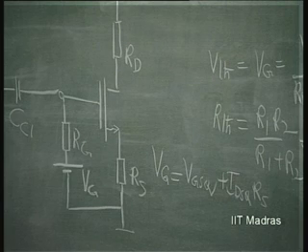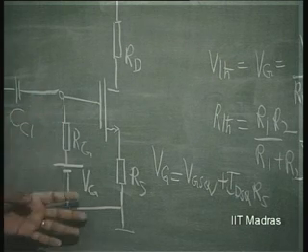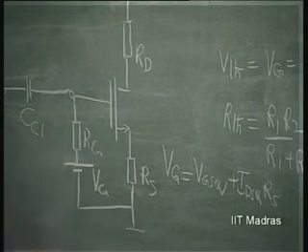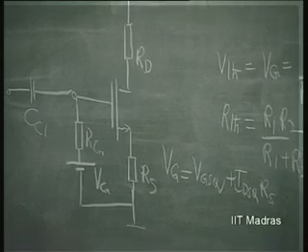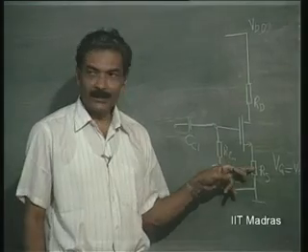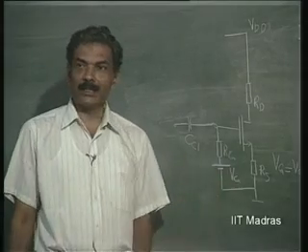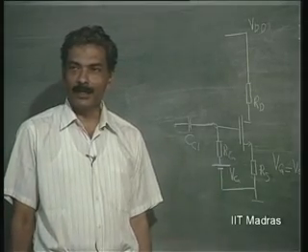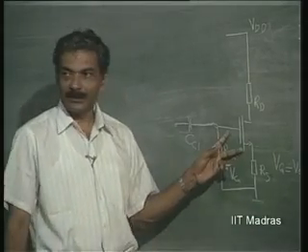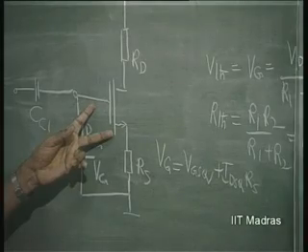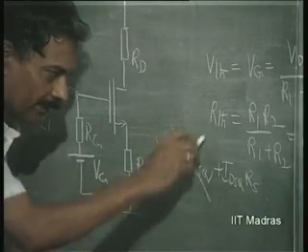Is this clear? This voltage earlier was becoming totally equal to VGSQ, that was giving problem. So, what I did was put a resistance in series with the FET, so that the drop across the resistance is dominant compared to the drop across this.